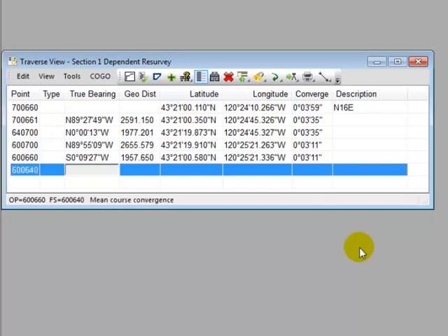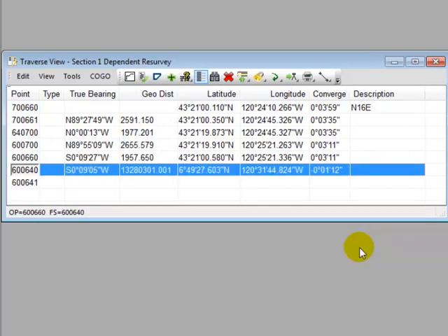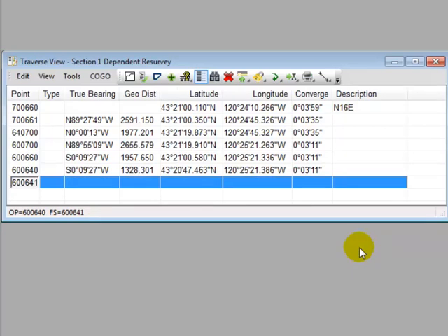Here I've already entered a bearing, and I'm extending that bearing along this west line as I head south. So I'm just going to press the space bar and then enter. And that recalls the bearing from up above, the previous bearing. I can do the same thing with distances or descriptions or whatever I might happen to have here. Okay, this is a regular 40, so 28301. We're pretty close to it. Well, let me go back and enter that. Now, if I entered something wrong, pretty simple for me just to go back and put the right number in. Press enter. Traverse PC recomputes for me.